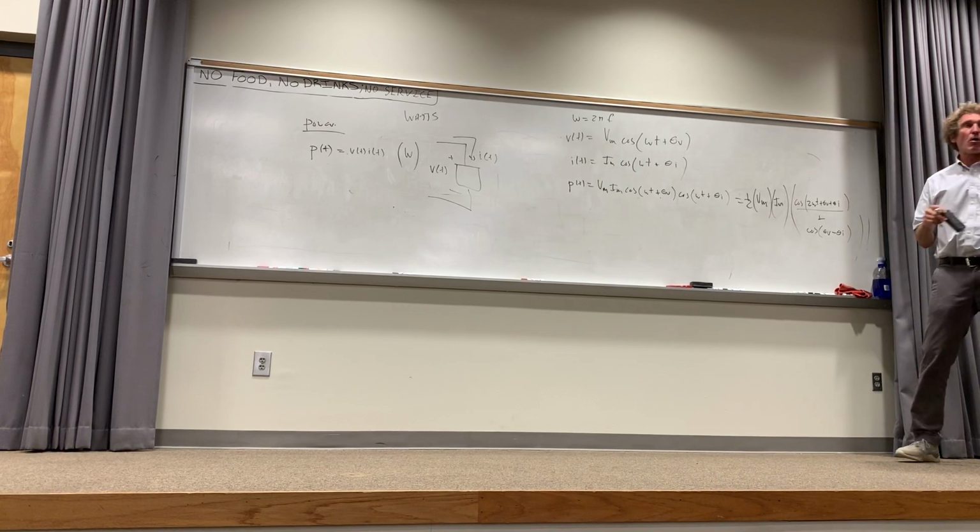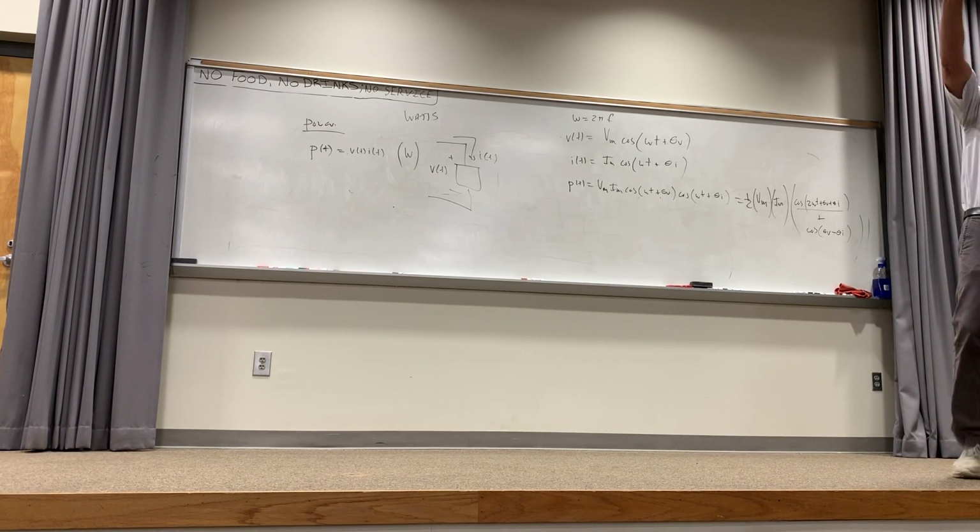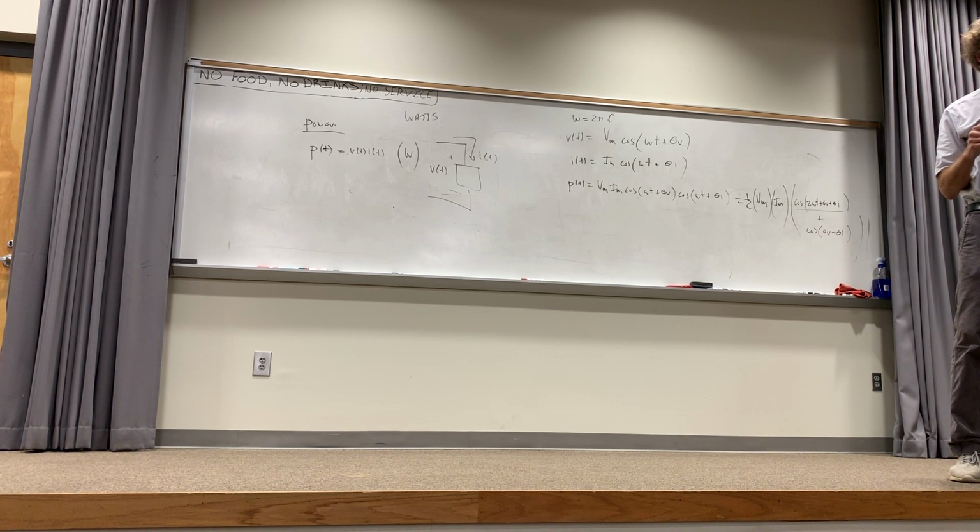If you look there, that's all voltage is 60 hertz. You see these lights up here? Those lights actually blink at a rate of not 60, but 120 hertz, because the power itself will be varying. It will go from 0 to peak to 0 again every half cycle, so they blink at a rate of 120 hertz.